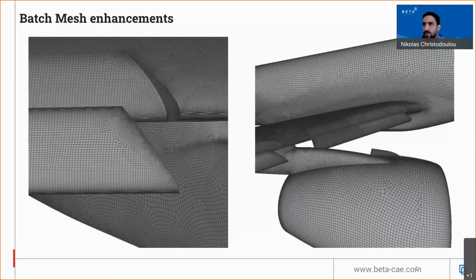Moving on, there are significant improvements in our mixed mesh CFD algorithm, especially for aerospace meshing. Using feature recognition, ANSA can apply an isotropic mesh treatment on leading and trailing edges, and at the same time produce zones around these features with quad elements. Based on our experience from the aerospace sector, we have concluded that the quad dominant mesh is very suitable for CFD, yielding less elements and more mesh flow alignment.